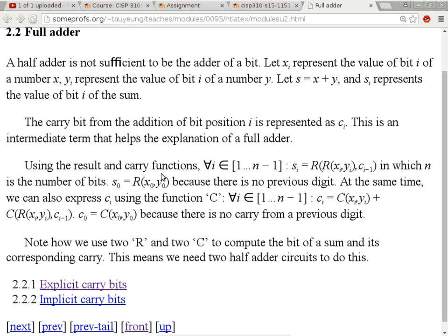So now your propagation delay is just proportional to the number of bits of your adder. Yep. So I think I'm just mixing up coding with this stuff. But so the OR gate, it's not working like the OR operator where... It is an OR operator. But so how, like in C, there's something called short circuiting. So once we get, for OR, once the... But in this case, you cannot short circuit, okay, that's what I'm asking. Because the availability of these two carry bits would not be at the same time.